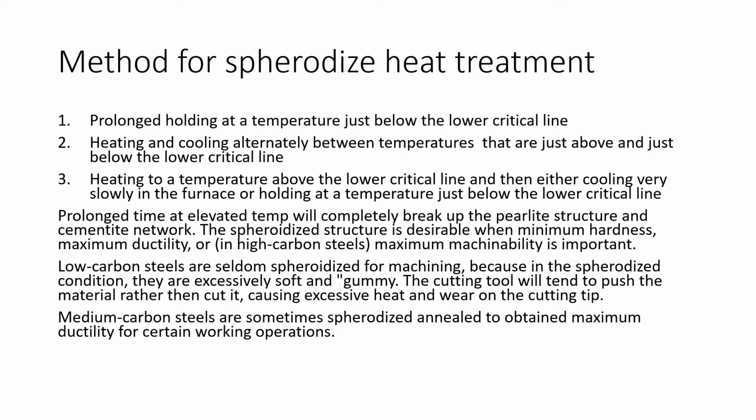Method for spheroidized heat treatment. Three steps are used for the spheroidized heat treatment. Prolong holding at a temperature just below the lower critical line. Heating and cooling alternately between temperatures that are just above and just below the lower critical line.